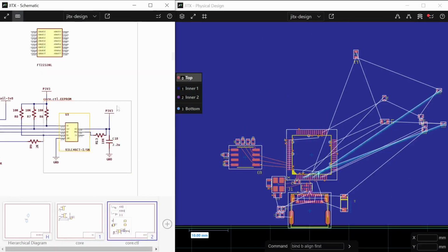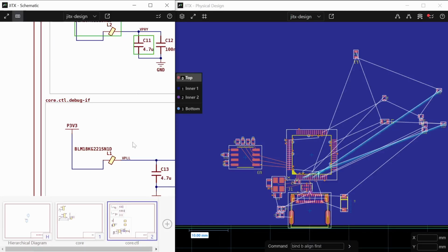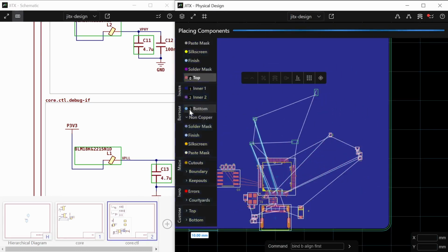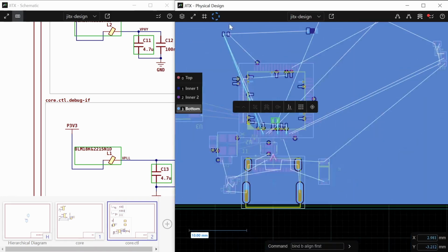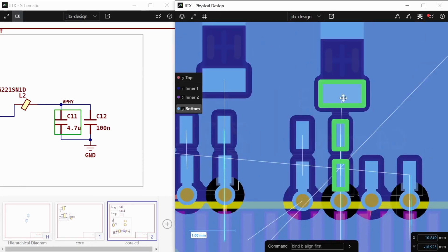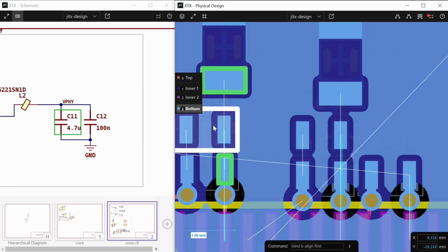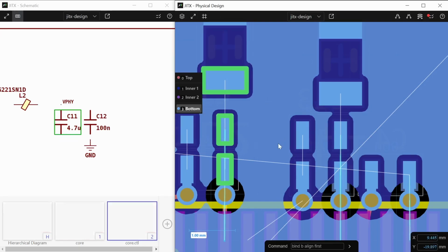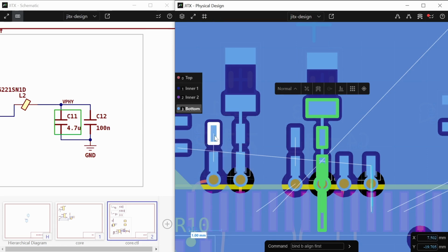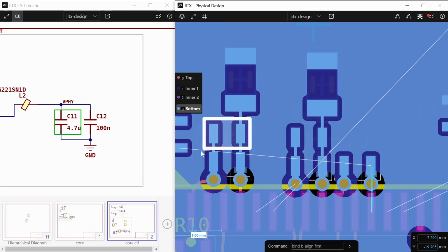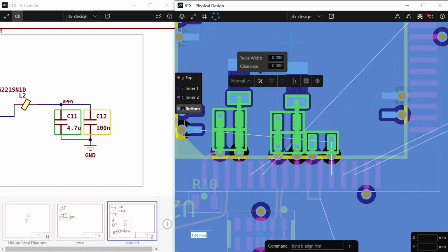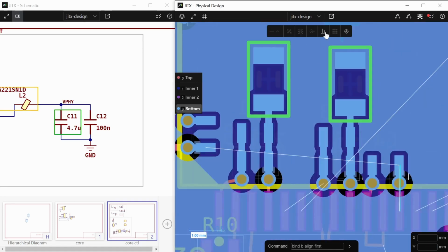So we'll select our power filter components here. Got this ferrite. And the capacitors. Flip those to the bottom. Go. And as before, select these, press B to align, select these, 1, 2, 3, press B to align, and you select a net, press A, press Q, and then press Q here as well to route the unfinished connections. And as before, we can select all these, make sure we have balanced copper by using a 0.2 millimeter trace width. And these we can align as well. Why not?